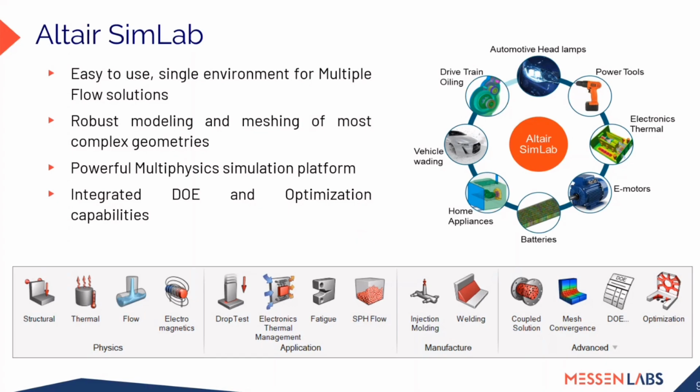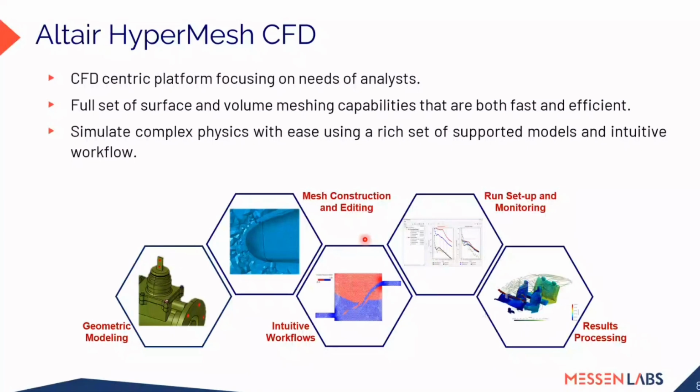Whereas in HyperMesh CFD, it is more on the AccuSolve part. You can perform flow and thermal simulations alone in HMCFD. So in that way, these two user interfaces are developed. Please don't get confused between HMCFD, SimLab, and AccuSolve. We have solvers and we have preprocessors. First, we do the entire modeling in the preprocessor, and then we submit the job to the solver.